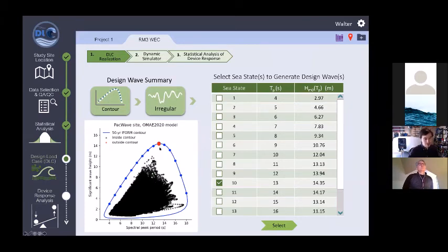But of course, the different systems are going to respond differently based on the frequency of the waves, and also the steepness of the waves, which is related to the frequency and height. We've had these smaller waves down here, but they're fairly steep. Those might be problematic for slamming and the like loading on the hull itself. But then these longer waves out here are probably going to excite the mooring system more, and those might be problematic. So like my previous answer, I guess it depends.